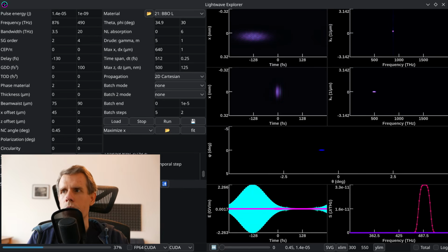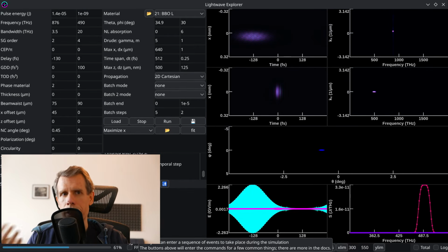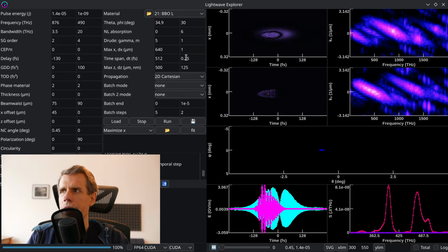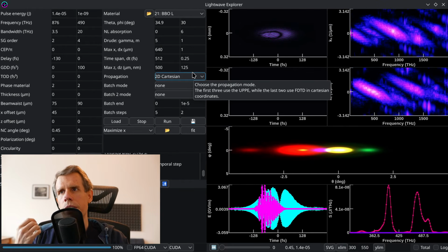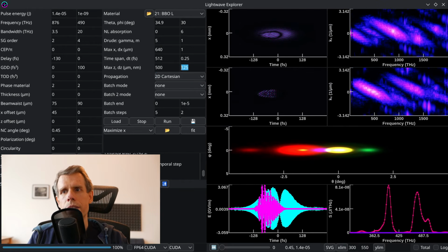And when you run the simulation, you can make sure that it also still fits. Then if you're getting a result, make sure that you can make all of these numbers smaller, all of these resolutions smaller, and still get the same result. And if you get something which isn't returning anything, you get this not a number error, the main thing to do is check in the crystal database where the Sellmeier coefficients, where the refractive index data came from.